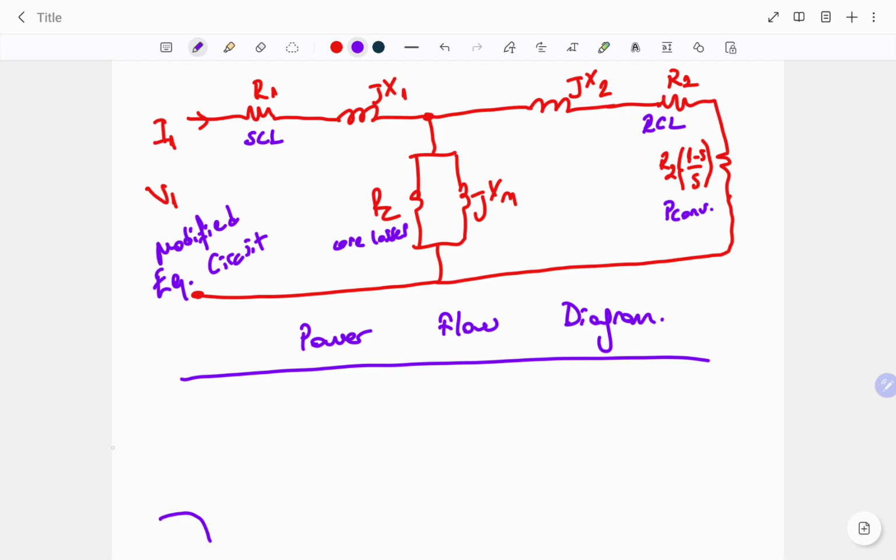So let's start with the input power. So we have three-phase system. We can use two different expressions to write an expression for input power. The first one can be the simple one, I think. V phase, I phase, and cosine theta can be multiplied by 3. So if you know the phase voltage and phase currents and the power factor, you can multiply by 3.